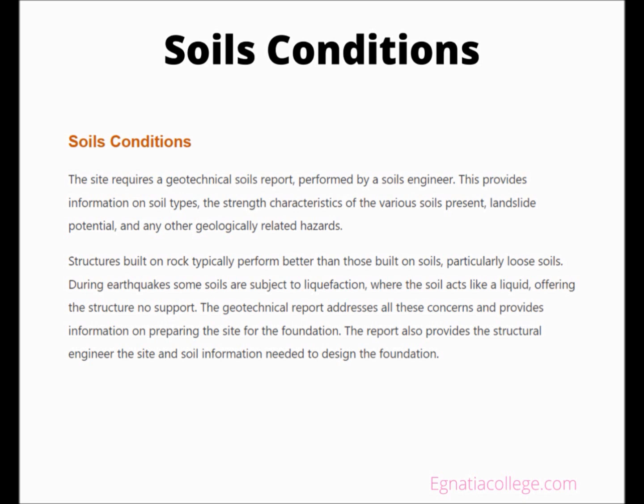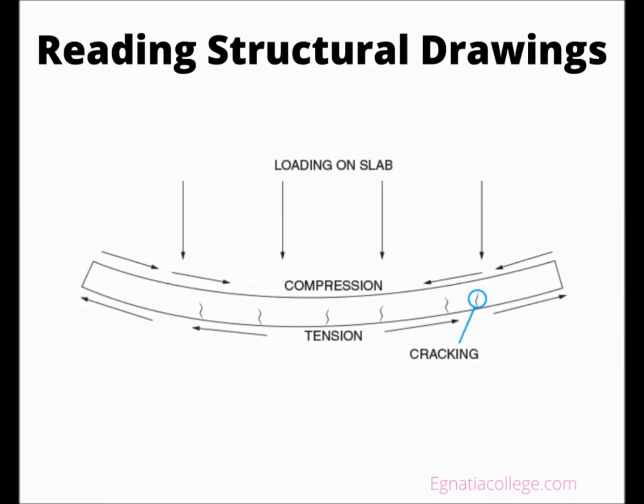During earthquakes, some soils are subject to liquefaction, where the soil acts like a liquid, offering the structure no support. The geotechnical report addresses all these concerns and provides information on preparing the site for the foundation. The report also provides the structural engineer the site and soil information needed to design the foundation.